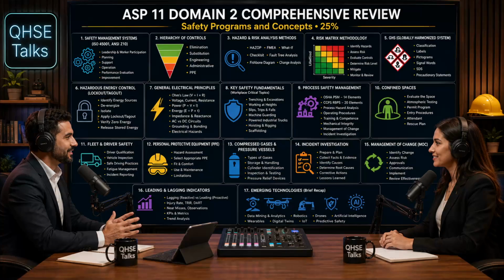Okay, let's jump over Part G, scaffolding, and move from lifting heavy things to preventing catastrophic chemical disasters. Parts H1 and H2, OSHA Process Safety Management, or PSM, and CCPS, Risk-Based Process Safety, RBPS. PSM is a direct regulatory response to historical tragedies, like the catastrophic gas leak in Bhopal, India, or the explosions at Texas City. The 14 elements of OSHA PSM are designed to tightly control highly hazardous chemicals.